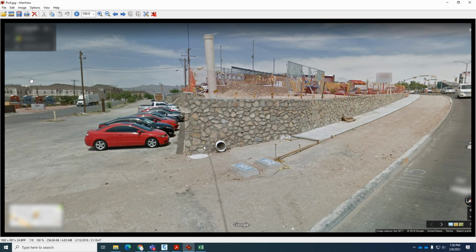And here, standing on the corner, you can see how much we're actually having to fill. Once again, that way you can park your car up in this area and walk up to the building nice and comfortably. Okay. Now, in some cases, we do have clients that tell us, no. Why are we filling all this stuff? That, by the way, is very expensive to do all this fill. And then we have to do this, what's called a retaining rock wall, which is a structural rock wall. We're talking tens of thousands of dollars.